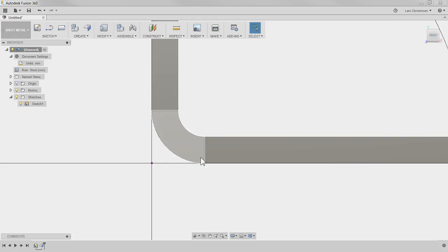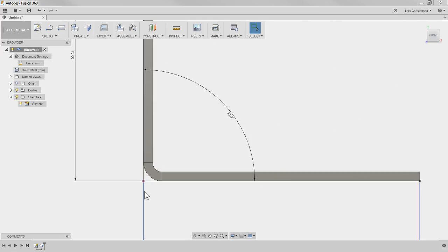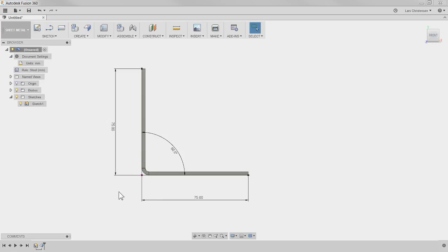What that means is that if this here is 75, and this is 75, your logic is saying, well, that's two sides of 75, that's 150 millimeters. But actually what happens is that when you bend that 90 degrees up, you're actually stretching the material a little bit. That means you actually need a smaller piece of material, less than 150, to get 75 by 75. Now, some of you might be thinking, well, does that really matter? Well, it does, even if this is just a 90-degree bend.